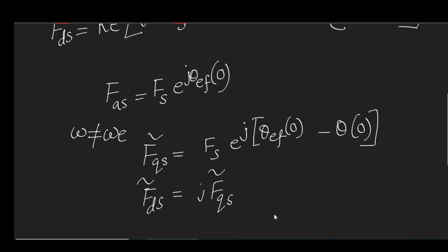And we are free to select theta_0, the arbitrary reference angle. Try to understand why we are free to select it. You cannot select theta_ef as per your choice, because theta_ef is the instant at which you are going to switch.